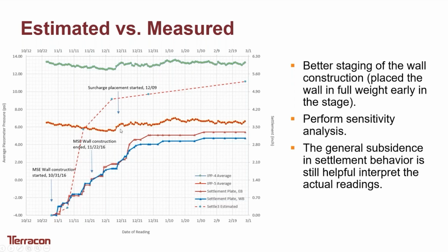But the most important comparison, looking at measured versus estimated, is that even for the estimated, I can see my curve is kind of flattening here. And I can confidently say that once I have these 3 or 4 back-to-back same readings, then I can say, okay, my surcharge has done its job. Now I can take my surcharge out and have my full pavement constructed.